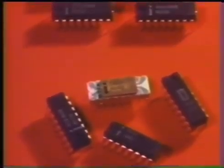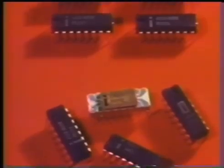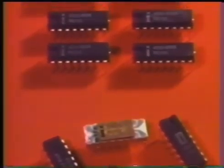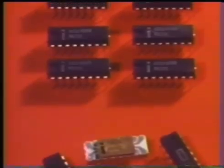The largest system you can build without adding extra logic consists of the CPU, 16 ROMs, 16 RAMs, and any number of shift registers. This is equal to 4,096 8-bit bytes of read-only memory and 1,280 4-bit bytes of random access memory.